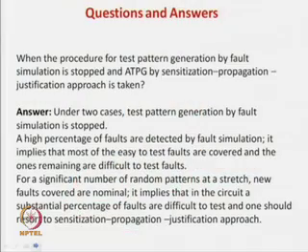And for all other cases like serial, deductive and concurrent, we do not at all think about the memory or the parallelism of the computer. We rather think about what the fault list size is, what the affected gate list size is, and accordingly we attach it to each gate or to the fault list. So, that depends nothing on the parallelism of the computer, it is just a program. We compute that for this fault gate list, these are the fault gates you have to add, that is, the fault version you have to add. For these gates, this is the fault list you have to add, we just keep it. We do not think about the architecture or the parallelism of the computer available, or how many fault lists we can add, nothing like that. This gate has so many faults in the fault list, just keep them.